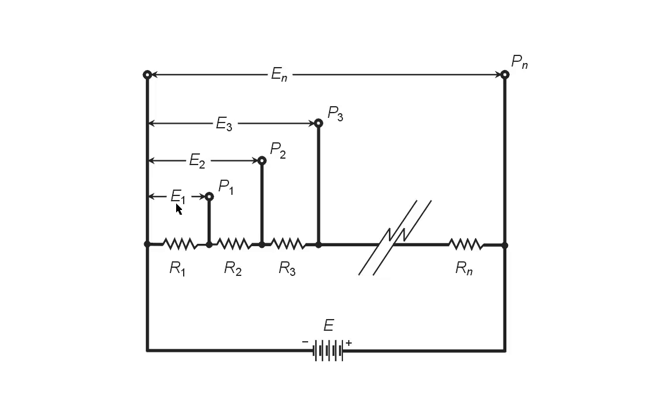And then, of course, we have voltages E sub 1, E sub 2, E sub 3, and E sub 4 that we can get across one resistor, just R1 all by itself, or the series combination of R1 and R2, that's the E2, E sub 2. The combination of R sub 1, R sub 2, R sub 3 in series will give us voltage number 3, and then the voltage across the whole thing is going to be the same as the battery voltage, and we are told that the battery voltage here is 18 volts. And then we're told what these actual voltages that we want are.